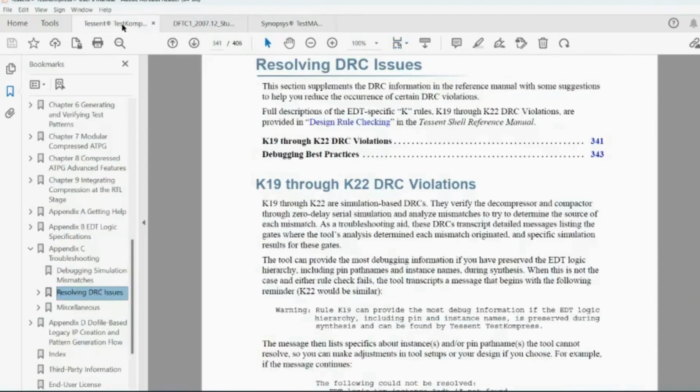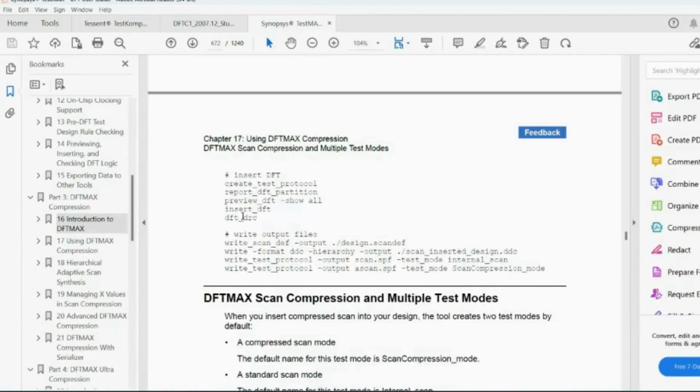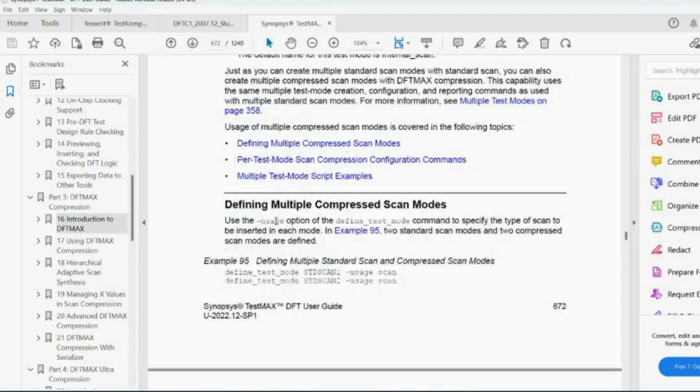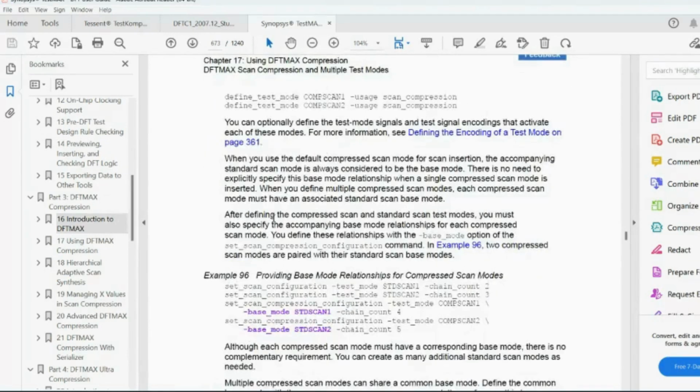Those violations are from Tessent. Tessent naming convention is T violation, trace violation. In Synopsys you will not see those violations. Directly after DFT DRC you will see if there are any chain blockages because of improper clocking information, control signals not provided properly, or any gating information that will end up as DRCs.